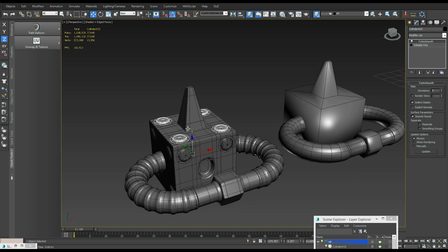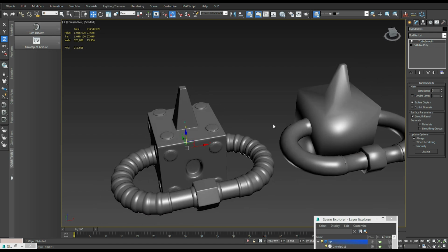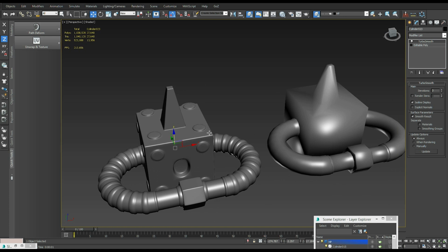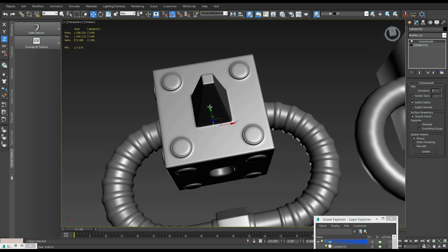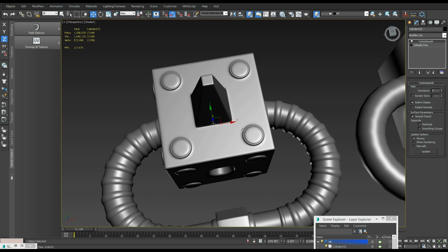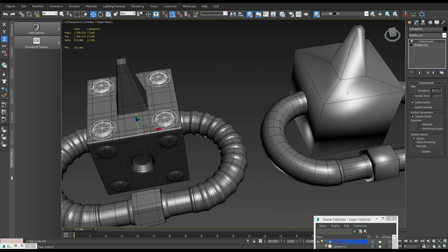One thing I have here too that I haven't had in my previous demonstrations is floating geometry. And so I wanted to talk about that. Basically, floating geometry is extra high poly geometry that's floating above the surface of a mesh, and there really isn't anything that correlates over to the low poly. What we're doing here is we're just straight baking this right into the surface of this cube. If you look in the viewport, if I zoom in on here, you can see that it looks like it was almost modeled straight into the surface of here. If I do a render, you can see that it looks like it was part of there, and that's also how the baker itself will see it too. So you take that normal information and bake that right down into the surface of the low poly over here.